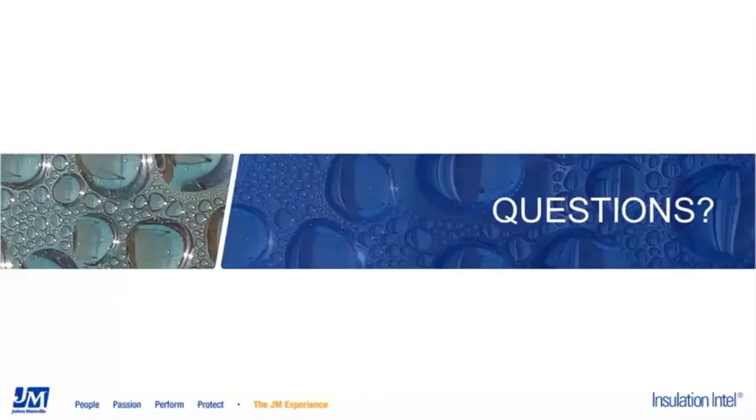So we would never recommend that you paint the facings on our pipe insulation because we don't know what that does to the flame smoke rating. Paint can serve as a fuel source. Because we don't know what type of paint is being used, you're going to void our manufacturer's warranty by painting that insulation. So we would not recommend that you paint it.